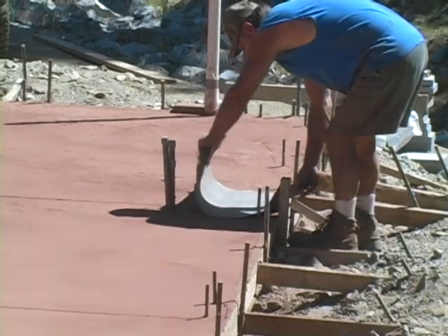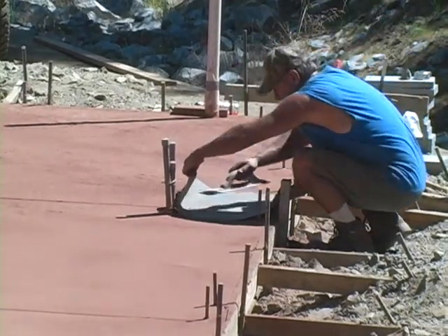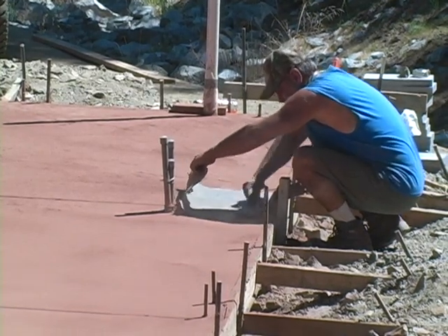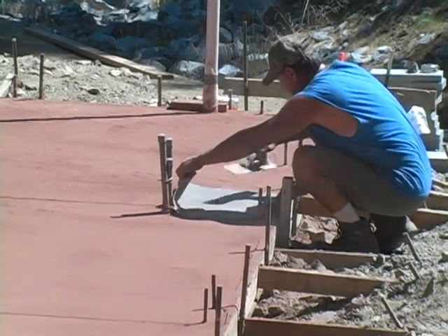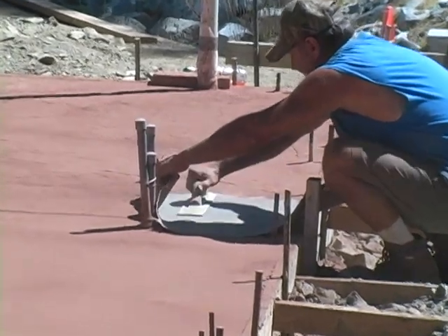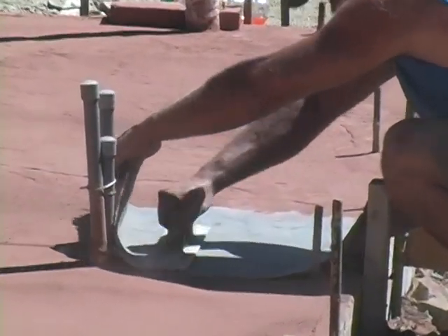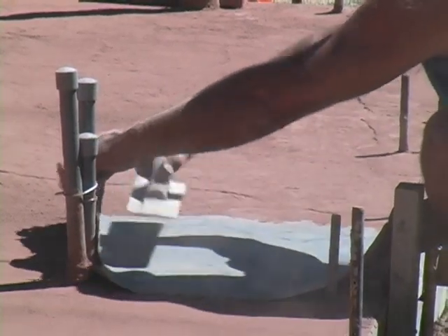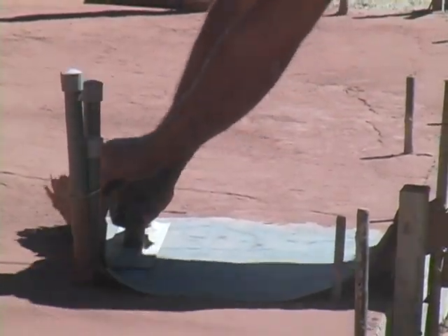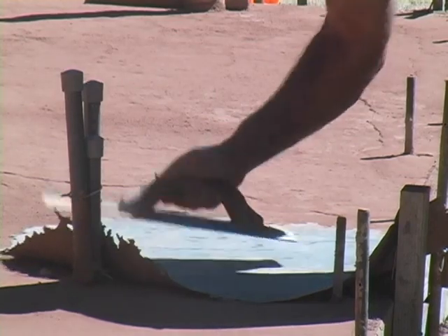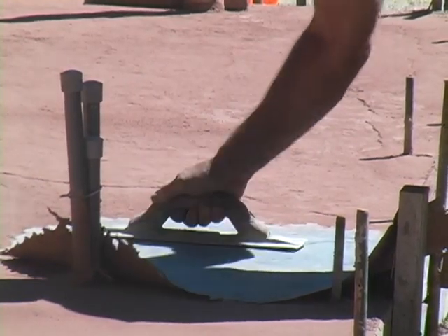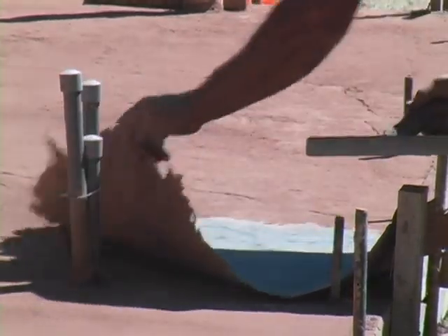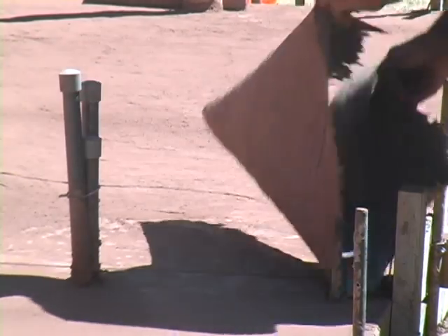For areas where the large stamp won't fit, we have the smaller secondary stamp that I showed you earlier on. Now again, you don't have to use the tamper. We're just going with a magnesium trowel and hitting it hard enough to imprint that pattern onto the concrete. This is a great thing to have for areas like this where you just can't get that large one in there. You can get the smaller one in, and it's a random enough pattern that you won't notice any difference when you take it off.